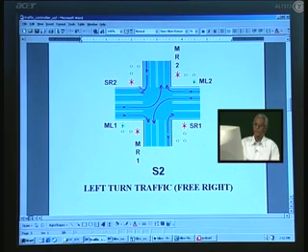And notice that one more white part is there. This is normally for parking. So, there will be another white line for closely here, and that will be the cycle lane. And normally when you pull onto the sides, you will have to see that it is after the cycle lane and right on the curb. So, the right side of your wheel will have to be within this 18 inch from the curb, and here I have assumed a free right turn, and therefore on all directions you can see a free right turn here, and what is depicted here is the left flowing traffic, left turn, and naturally this is the right flowing traffic.